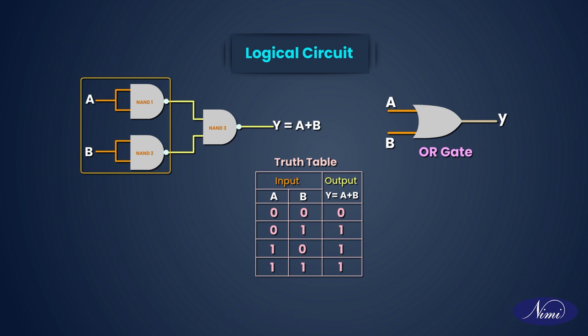Inputs A and B are fed into separate NAND gates first, which invert the signals. By then NANDing these inverted signals in a third gate, the cascade of NANDs serves to invert the inputs twice, reconstructing an OR logical function.